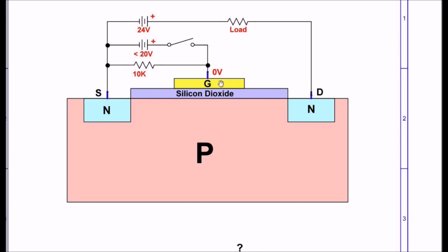The gate is nothing but a thin metal layer, and you have an insulator between what is essentially P material. With no charge on the gate, there is no current flow possible under this setup, because if you go over here, this here forms a reverse bias diode, thus it will not conduct on this end.